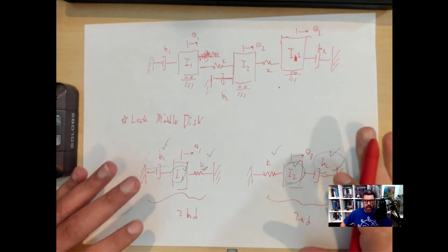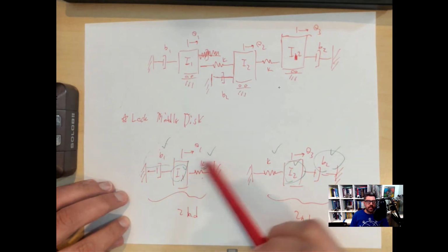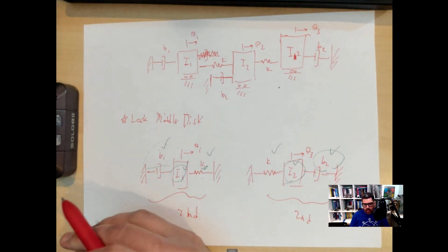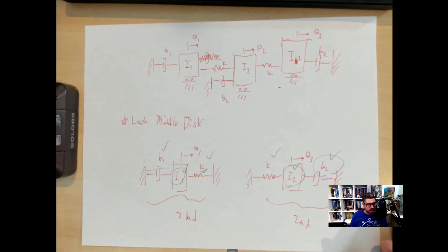All right, so now comes the challenge of finding the coefficients. Now, there are two ways to find the coefficients. There's an experimental way. If you have the physical device that you're trying to estimate the parameters of, then you can do it via an experiment. Excite it, do a step response, look for overshoot, settling time, rise time, which we saw in the homework.